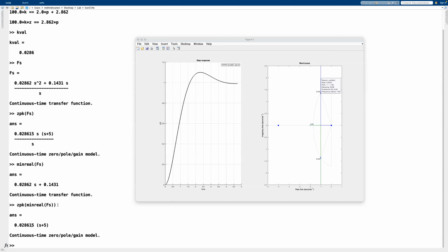0.0286, so that you can achieve this settling time and overshoot, or in other words, you can achieve this zeta and omega n value exactly. And this is the best case. You can see that the settling time and overshoot values are quite close. You have overshoot of 10%. The settling time formula has a bit of an issue on its own, but instead of 4, it gives out 3.5. If you remember the week where we discussed this, it has its own nonlinearity, so we're just happy to use it for reverse engineering, sort of. So this is basically the best we can get here, but this is not always the case.